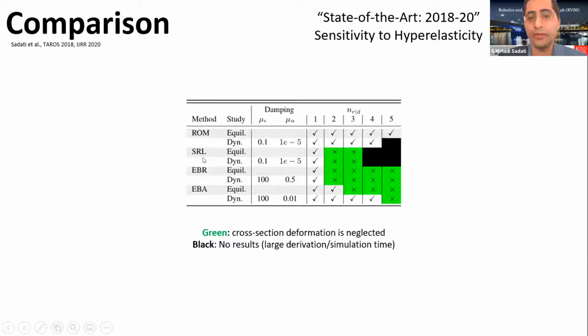But as soon as you use relative states, it becomes sensitive to change of parameters, introducing nonlinearity in the system, etc. So my favorite is basically Euler-Bernoulli with absolute states if you don't design a controller, and reduced Euler modeling with parameterization of the shape if you want to do the control design. But it really depends on your application.